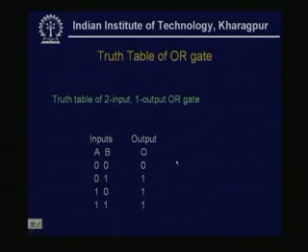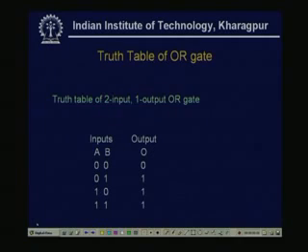Okay. Then what will be the truth table? In a similar way, this is a 2 input A B and output O. So, if we draw the OR gate, this is a 2 input OR. Now, input lines I have given A and B and output is O. If A B is 0 0, then both the switches are disconnected, so output will be 0.